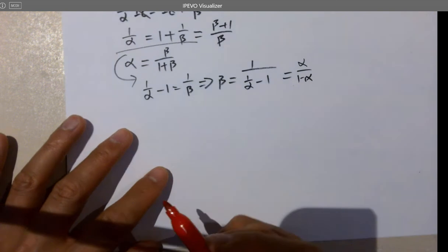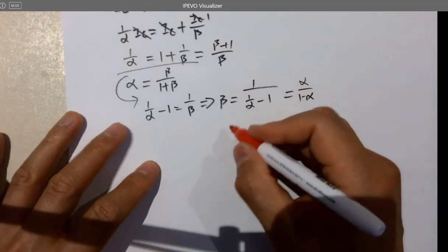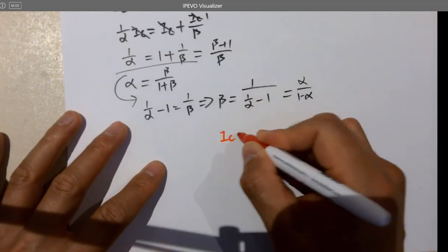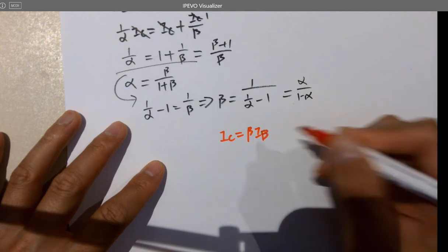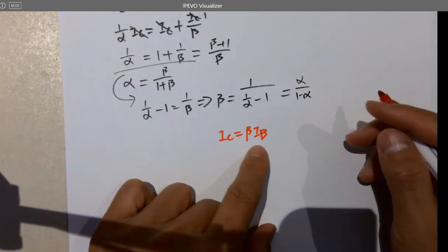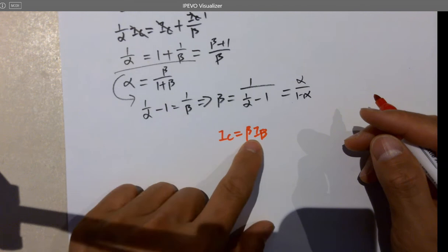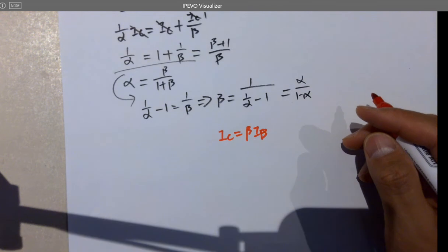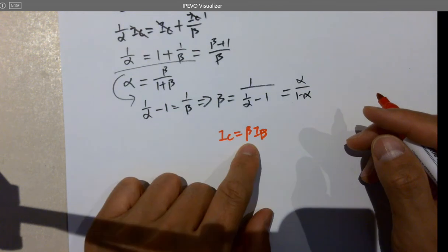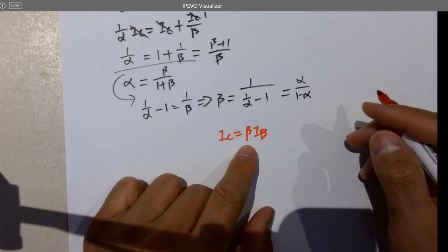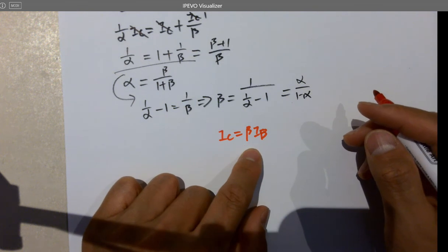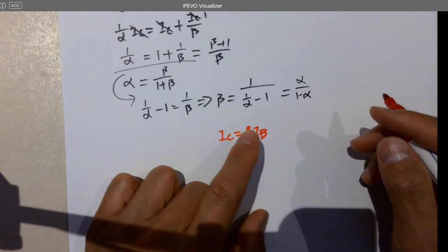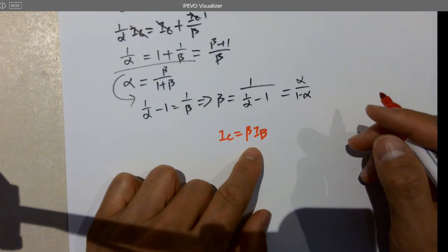The conclusion, so after the calculations, first, IC equals beta times IB. That's the main reason why we want to use BJTs, because amplifying the little current being injected into IB and amplify it by beta times, and beta is usually 50, 100, 200 times. First one you need to know, and the most important one you need to know about the BJTs. Okay, IC equals beta times IB.